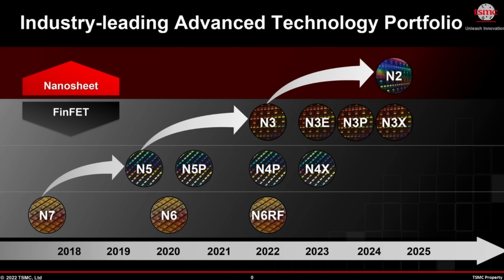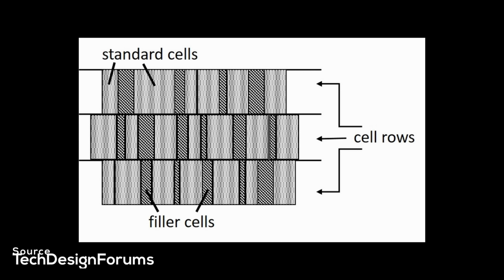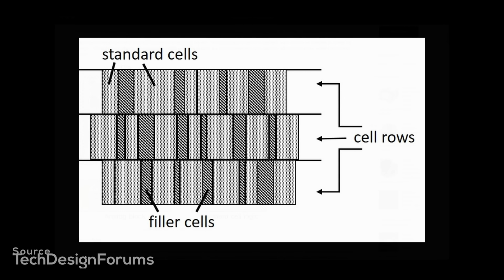Less important areas of the chip might even be best suited for the half-sized cells, because we don't need a lot of current there. Even if we had infinite die space available, using only large cells would lead to a very high power consumption, something we want to avoid. Once we have chosen the standard cells we want to use, we have to place them on the chip next. Something that of course doesn't happen at random, there are always rules to follow. Standard cells are placed in so-called cell rows, which is exactly what it sounds like, a row of standard cells next to each other. And many of these rows combined form a so-called logic block.